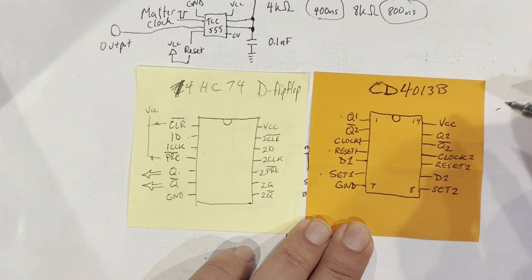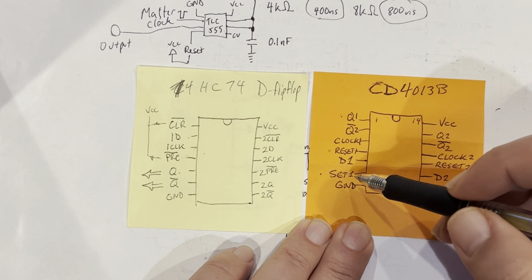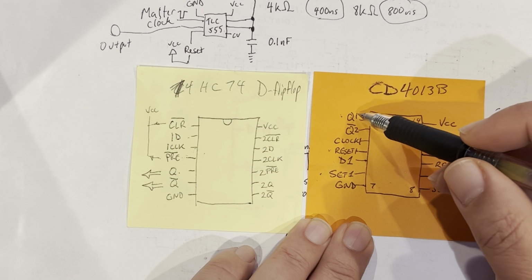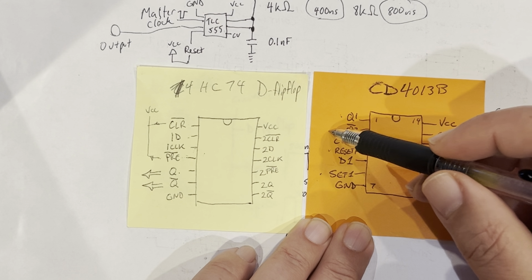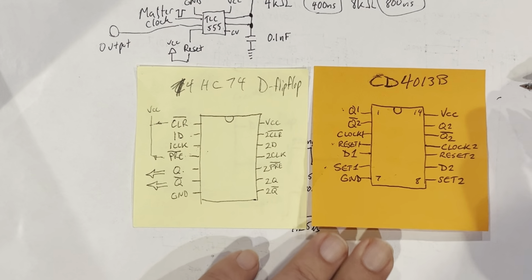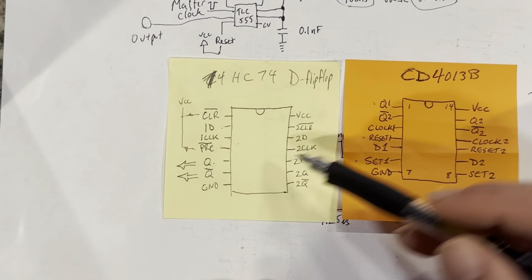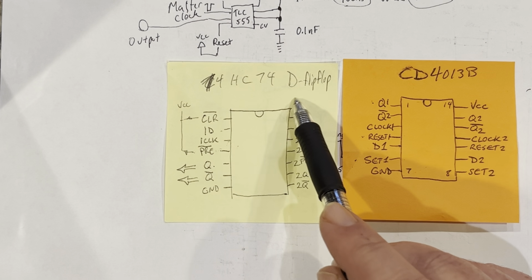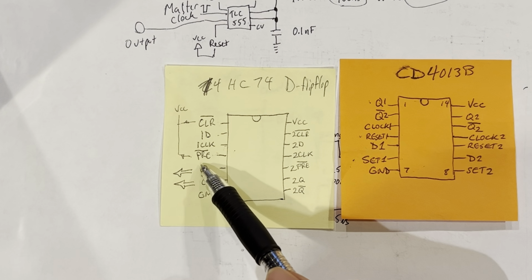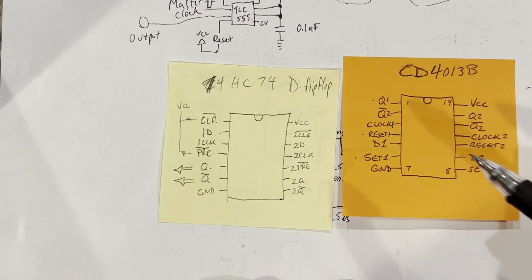And when I did that, and I would send a set signal, and then a reset signal, and then the reset would automatically go, and I measured the output at Q2 or Q1, it would give me about 800 nanoseconds. And that was great because that was my high pulse. And then when I did the same thing on this D flip-flop, it worked just as well as this one, but it was a little faster. And when I did it to this one, I got a low pulse, or a pulse of about 400 nanoseconds.